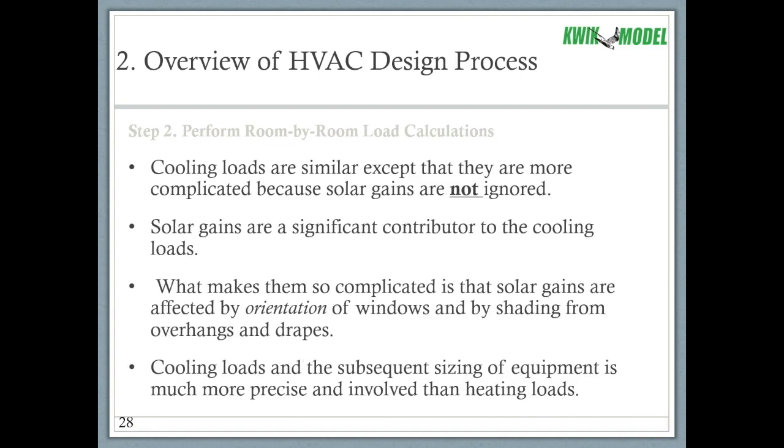Cooling loads are similar, except they are more complicated because solar gains are not ignored. Solar gains are a very big part of cooling loads. That's the sun shining into the windows, that's the sun beating on the roof of the house and that heat getting into the attic, that's the sun shining on the walls and warming up the walls, but mostly it's windows. So solar gains are a significant contributor to the cooling loads.